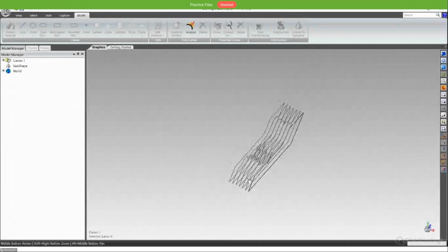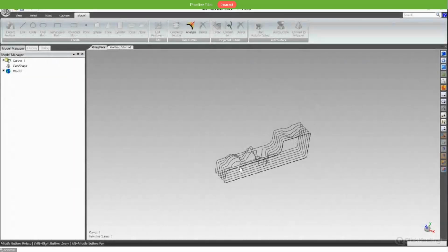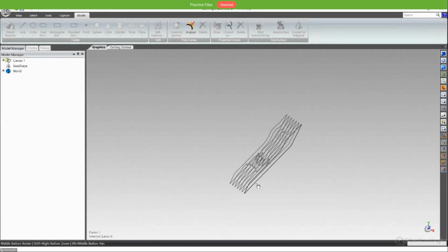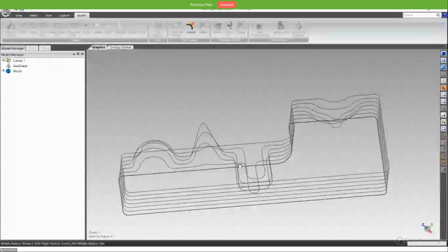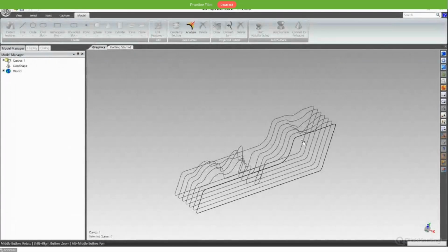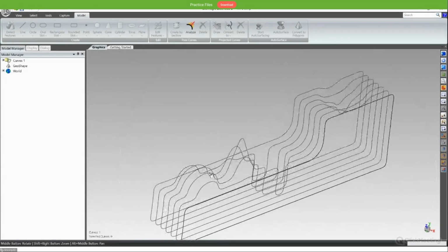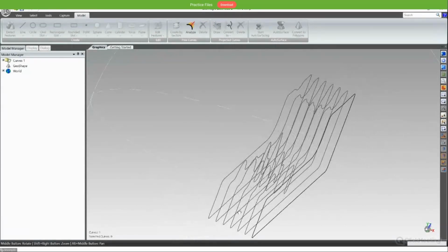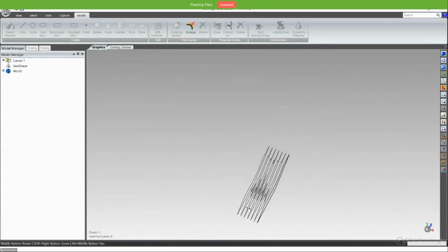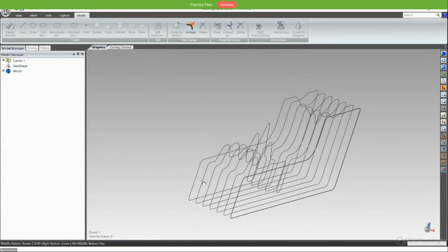That function will connect two lines with a surface. Like here, we have all these section lines, and I export them to Solid Edge and use the blue surface function. So I will have a model, since between these two section lines there will be a surface connecting the section lines. All right.